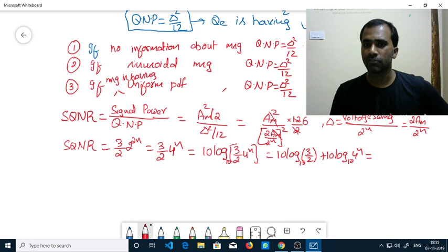If you are trying to find the dB scale values for first order signals like voltage, current, then you have to use 20 log. Whenever you're dealing with second order terms like energy and power, use 10 log. Whenever you're dealing with terms like voltage and current, use 20 log.